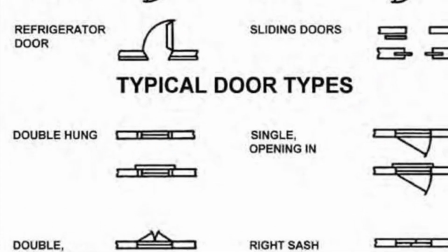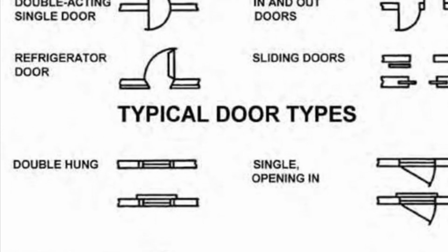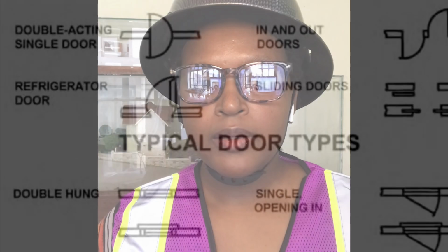You also have door symbols, where doors are annotated by a large gap between the walls and a curved line showing the direction of the swing. Say it can depict double doors or bifold doors, the ones for the wardrobe, or triple hinge door swings. So all this is depicted in the drawing in a different way.